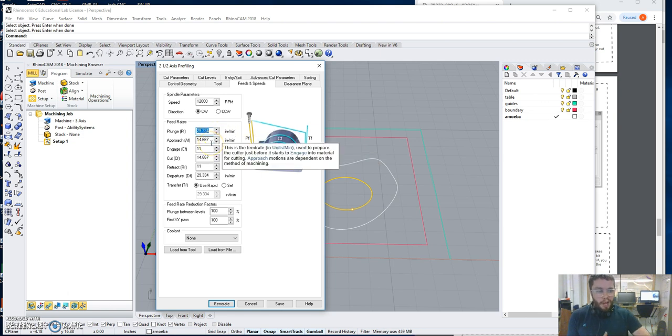For plywood and a 1/4-inch bit, I have listed 240 inches a minute cut speed, so feel comfortable using that for all the cut speeds. Jump cut, it strikes me that I just said cut speeds, which is why I mentioned that the terminology is ambiguous. Cut speeds is the same thing as feed rates. Spindle speed is always called spindle speed. You'll hear the words go back and forth. All you need to know is that that spindle speed is always 12,000. The cut speeds, feed rates, whatever you want to call them, are the ones that change for every cut.